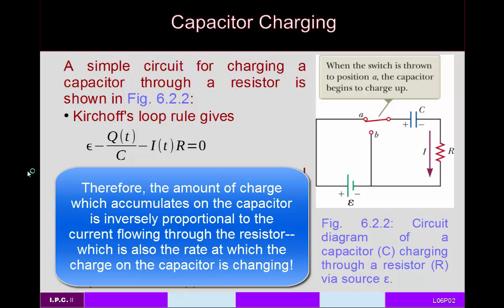We'll start with how a capacitor is charged and how to model the charging of a capacitor. What you see here to the right is a simple circuit for charging a capacitor. By the way, this right here is a switch, so if we switch it, this part that's in contact with A will switch to being in contact with B, and so the loop no longer has a battery in it. The loop will just be this part. Right now the loop is around like this, and you don't really get current flowing to B.